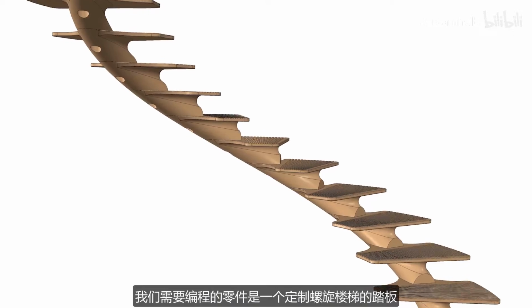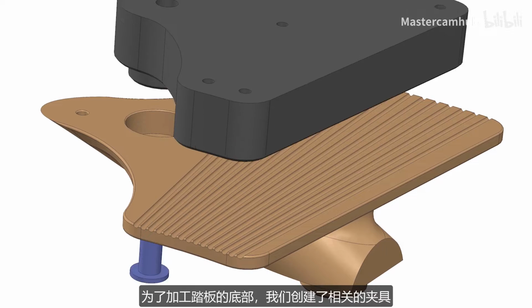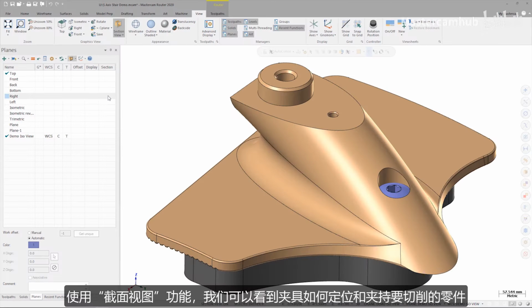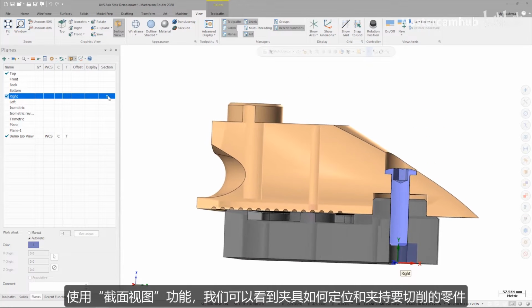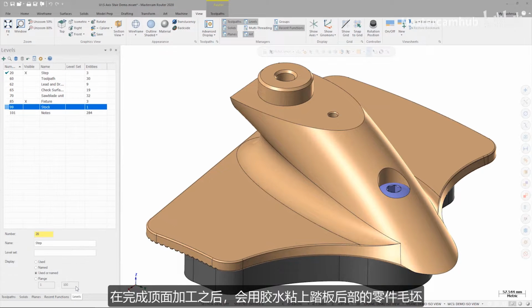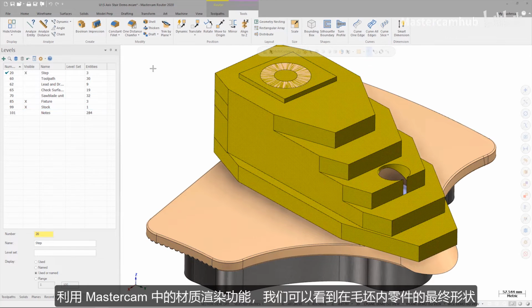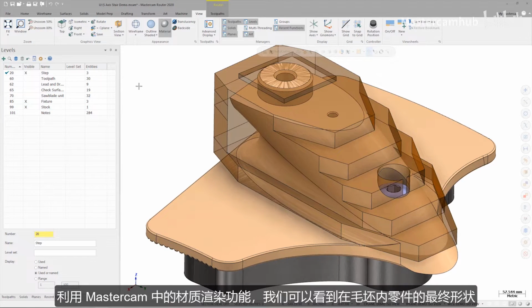custom spiral staircase. In this example, the top of the tread has already been completed, and a fixture has been created to hold the tread while the bottom's machined. Using section view, we can see how the fixture locates and holds the part to be cut. The stock for the rear of the tread is glued on after the top of the tread has already been machined. Utilizing the material rendering settings in Mastercam, we can see how the part geometry fits within the stock.